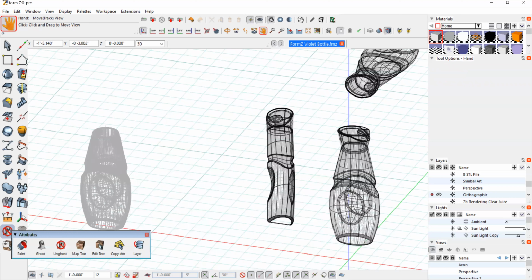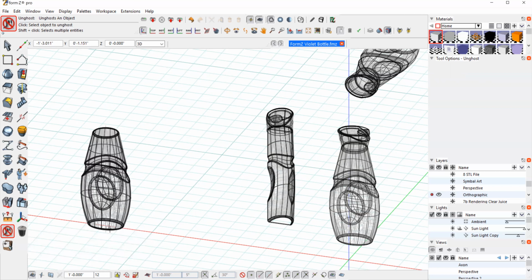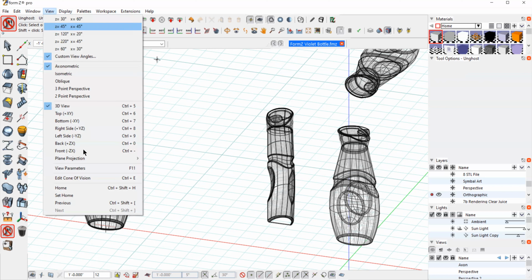So I have this set up over here. This is another copy of the bottle I have. This particular bottle, I have a wall thickness. I got this from the tutorial I did on doing a rendering in PET, where I actually created a wall, a thin wall, which is a realistic wall of about 35 thousandths of an inch. So I have that in there. It's not necessary for these other views. That can be solid because we're just doing the exterior dimensions. But for a cross section, we need to show that wall thickness.